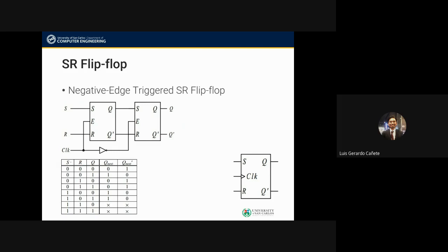So this is sort of like a combinational circuit table, wherein if we know that S is equal to 0, R is equal to 0, and Q is equal to 0, then when the clock comes, the Q next, the value of Q, will be just 0, right? So 0 and 0 on the set and reset will just copy the value of Q. So if SR is 0 and Q is 1, when the clock comes, we just copy the value of Q.